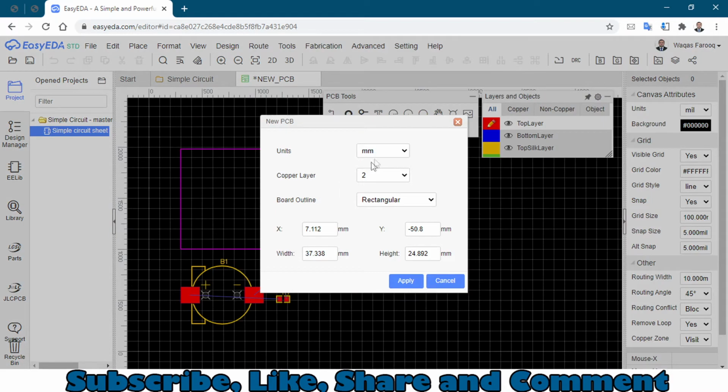Now we have the PCB, and now you will see the PCB size unit, which I will be using millimeters. And copper layers, I will use a simple 1 layer. You can use 2 layers, 4 layers, up to 34 layers PCB, but I'm using 2 layers. And rectangular shape, you can change to circular, rounded rectangular or custom. I will use rectangular, simple as that, or we can make a circular shape if you want. And this is X place and Y place on the graph, as you can see on the background. I will just change into plus 50, and there is a different height for this. I will click on apply.